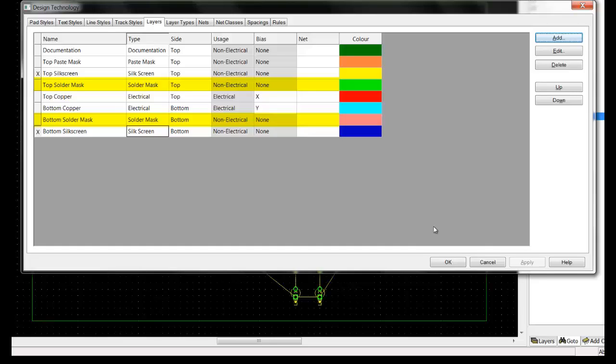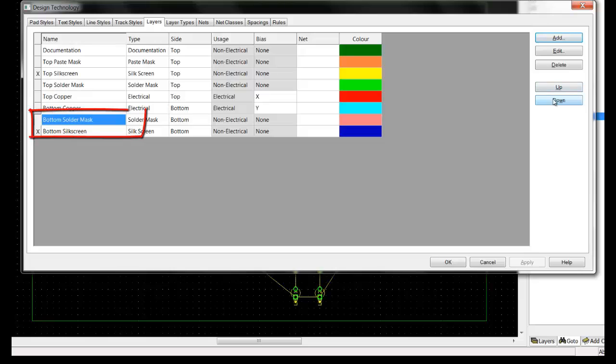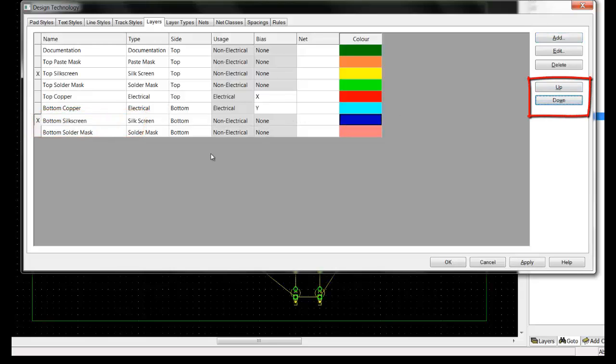This is the solder resist layer, which helps to define the solder areas, which is particularly useful for fine pitch and surface mount components. Copper layers are our copper tracks, component pads, vias, heatsink areas, etc. Should your layer order not be in a desired order, simply left click to select, and we use the up and down buttons to reorder.